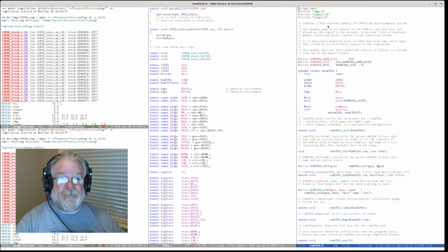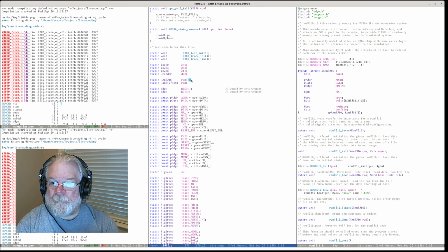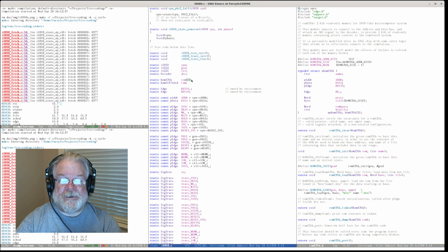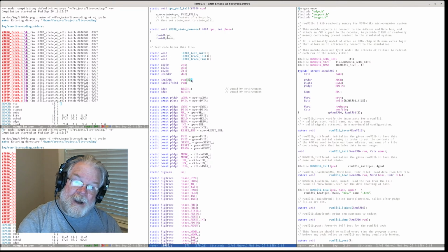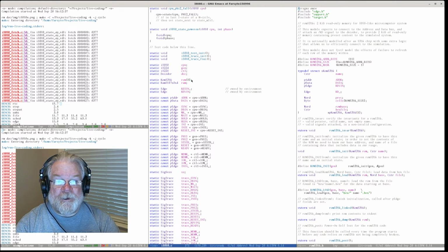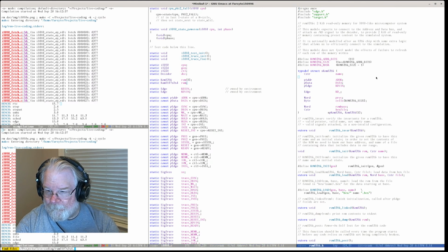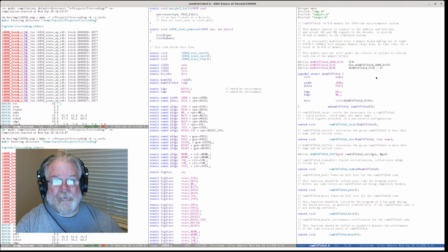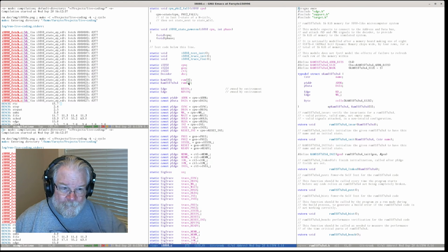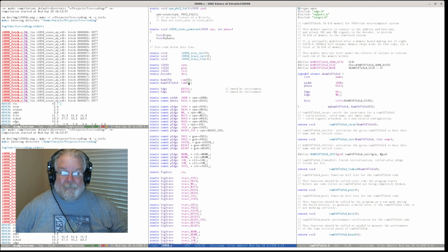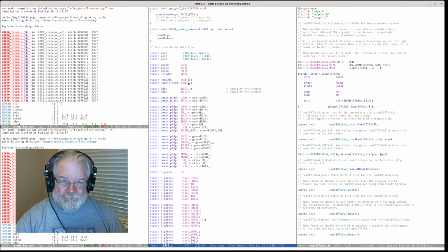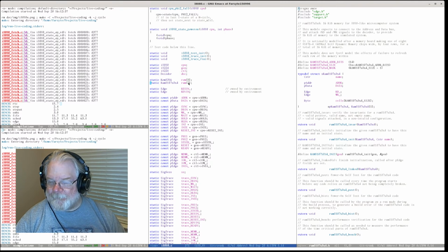The ROM is a 2 kilobyte read-only memory. I'm going to have 8 of them, giving me a total of 16 kilobytes of read-only memory, which I'll put in the top 16 kilobytes. And RAM is a 16 kilobyte memory. I'm going to have 2 of those, which I'm going to map into the low 32 kilobytes of memory. So this is actually a fairly deluxe system.